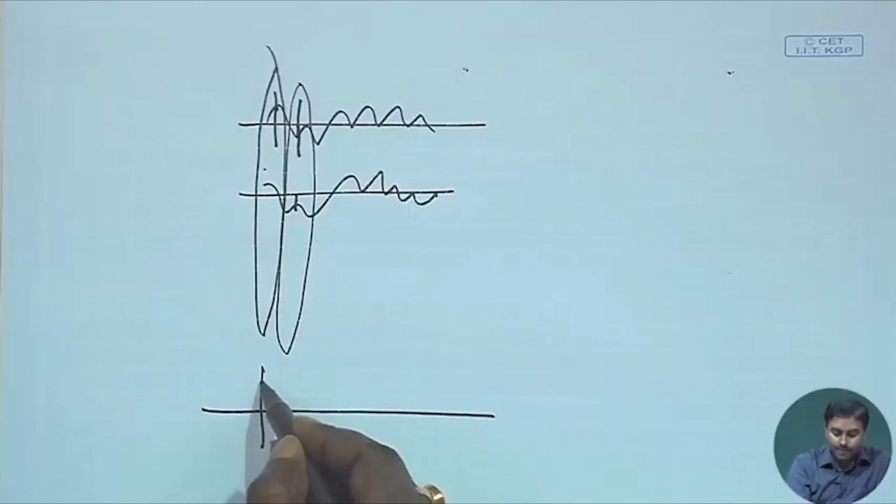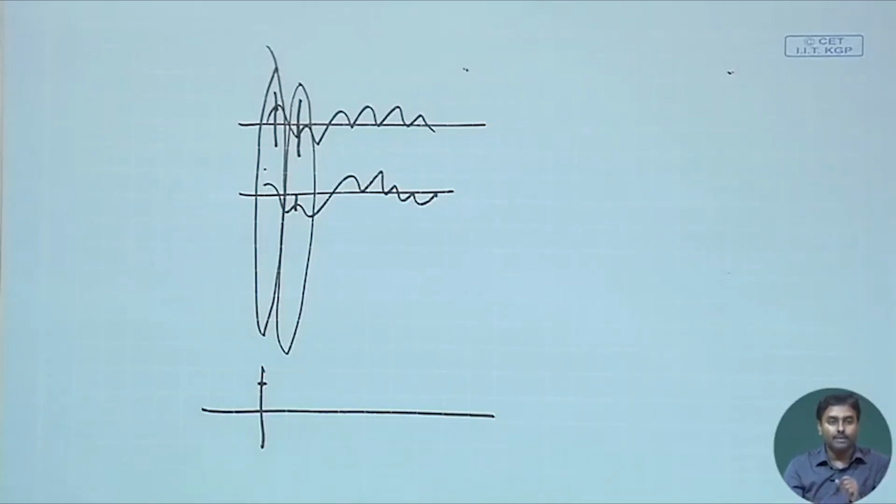Another time I take a snapshot, I immediately generate another random variable with a different set of values. These two things, are they dependent or are they not dependent? Because that also comes out from the signal quality or signal specification and that characterizes the signal as well, because if there is a dependency I need to know what kind of dependency. Okay. So, it might happen that the signal, even though it is random, at a particular time has picked one random number, but at the next time instance, because of the low pass nature, that means the signal does not vary too much. Okay. So, low pass nature means what?